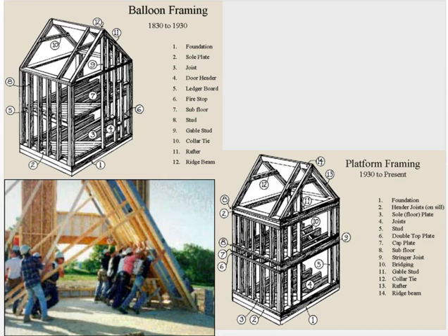Another image of the same, so our balloon and our platform there. And here they are raising a balloon frame. So the balloon frame is all but obsolete, very rare, but a condition where you typically find it would be in a two-story foyer, for instance, which you would refer to as being balloon framed.